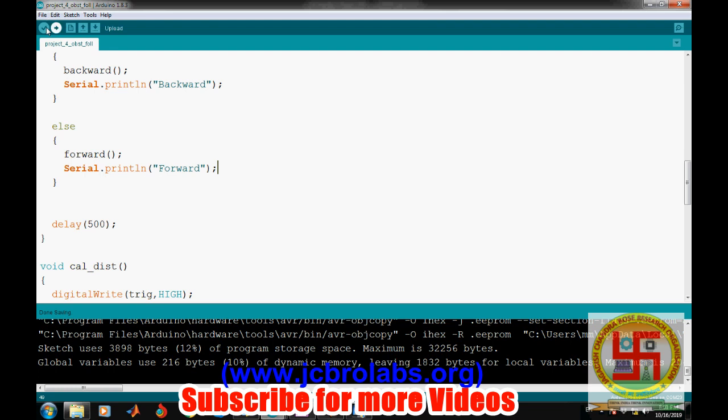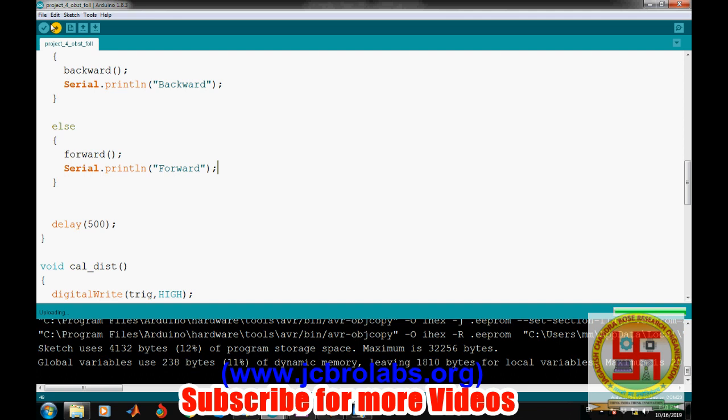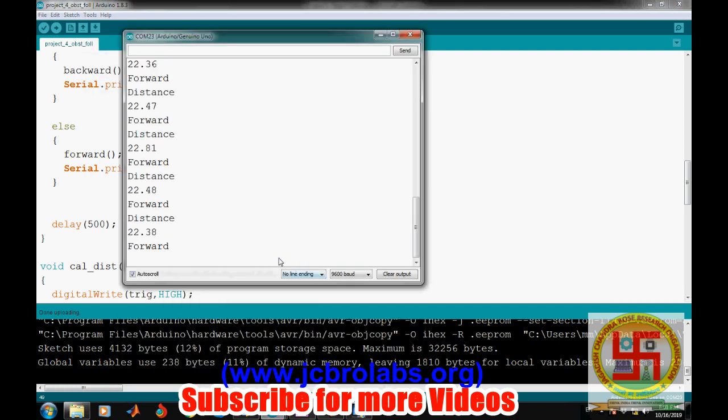Let's upload the program and see what it is saying. Right now our robot is static, we are just testing it. Let's open the monitor. The distance is greater than 15, so it is moving forward. Now the distance is less than 9, it is moving backward because right now it is very near to the object. And if the distance is in the range of 9 to 15 it should stop. So the program is working fine.